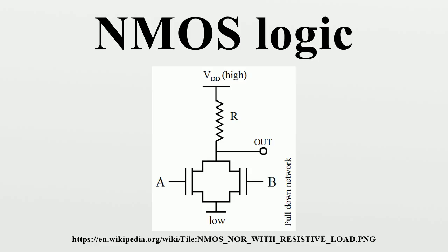high transition takes longer. Using a resistor of lower value will speed up the process but also increases static power dissipation. However, a better way to make the gates faster is to use depletion mode transistors instead of enhancement mode transistors as loads. This is called depletion load nMOS logic.